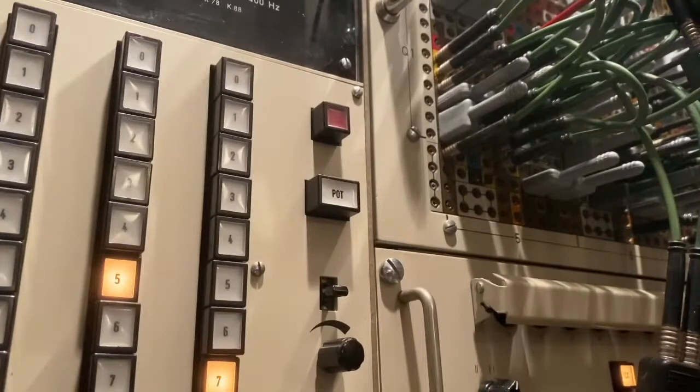With an analog computer, which works with voltages or currents representing values, your values are restricted to a certain interval. And typically one thinks in an interval of -1 to +1. So regardless if you have a transistorized analog computer, a highly integrated analog computer, a vacuum tube-based analog computer, from a programming perspective, you always think of every variable being in the interval of -1 to +1.